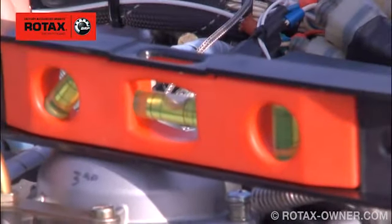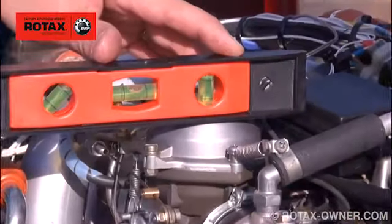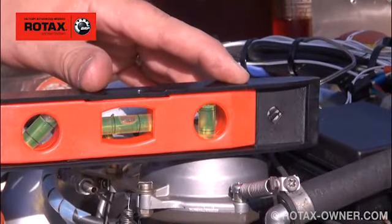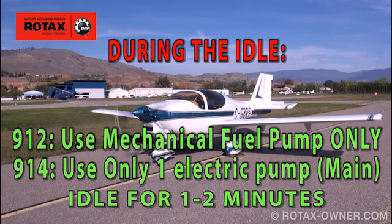Bring the float chamber to horizontal position. Level the aircraft if necessary. Start the engine and let it idle. After 1 or 2 minutes at idle, shut the engine off.